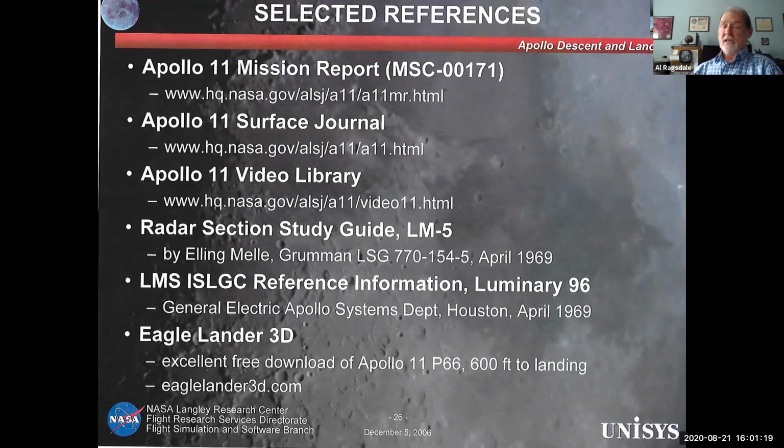The ascent stage was not, because it was very light and it had those very high acceleration rates. So in anything other than that pulse mode, it was almost impossible to fly it manually, to just move the stick and point it like you would an airplane. So that's why they liked that minimum impulse mode, so you were doing it in little discrete steps instead of slamming it around.